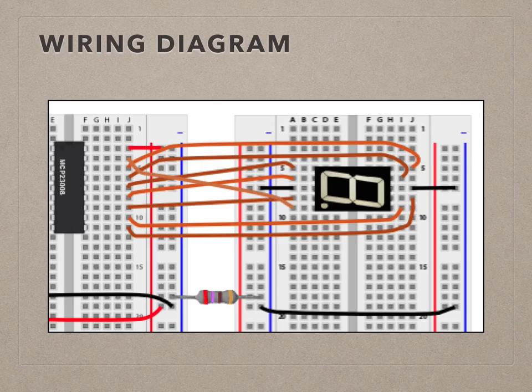Note also that the ground rails for my display are isolated by a single 270 ohm resistor, which links back to the other breadboard where the chip and the Pi are connected. I have used a 1 watt resistor for this purpose.